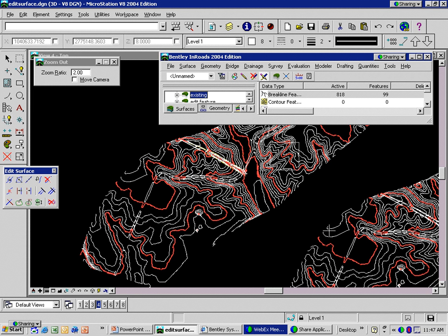The interesting fact is if we look at this DTM over the original one and snap to it, we have an elevation of 295 on this contour. If we go over to the next one that we just transformed, it's 495. This is a nice way to redisplay all your contouring. You're not tied to your existing contouring. You could just easily make the vertical datum change, and you could progress with the actual design of your project.